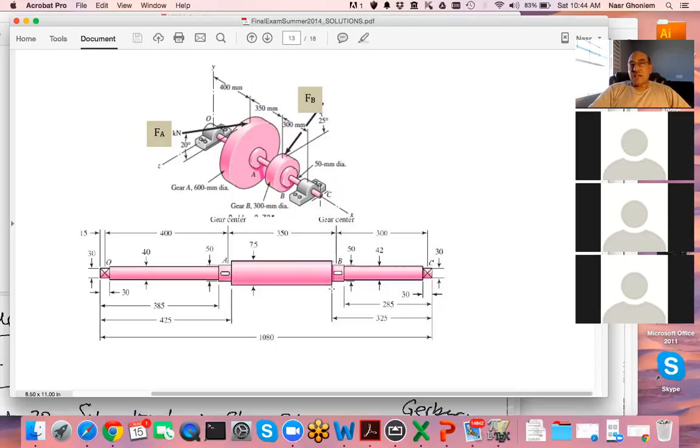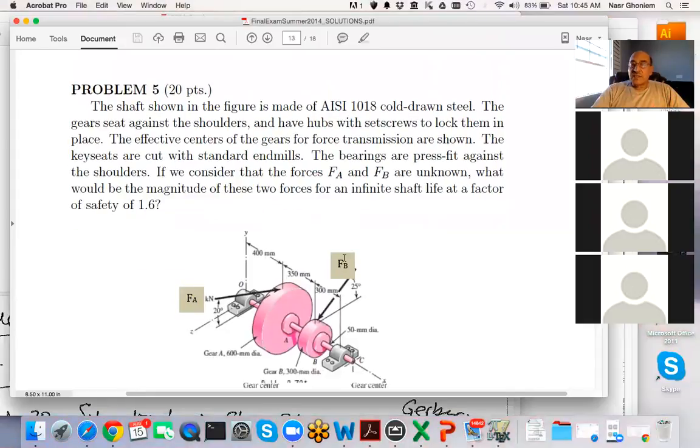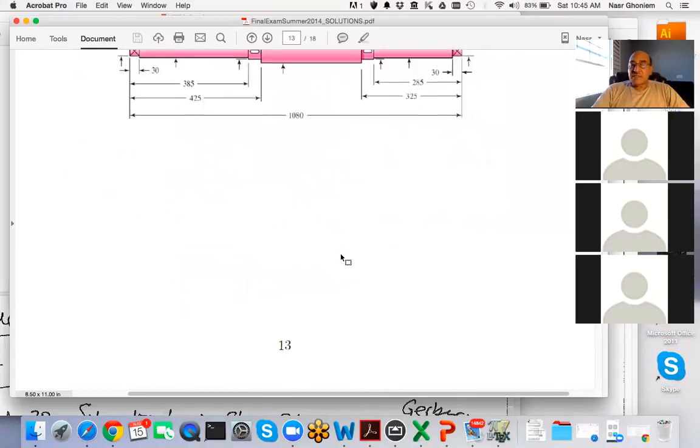So now we see that the stress has to be dealt with in the same way as we did in failure theories. So now we have to combine the alternating stress and the constant stress using the concepts of failure, either the distortion energy criterion, maximum shear criterion, Coulomb-Mohr, and so forth. Usually we use the distortion energy criterion to do that kind of combination. So this problem here is much closer to your final end goal in shaft design for power transmission, because it combines a number of elements.